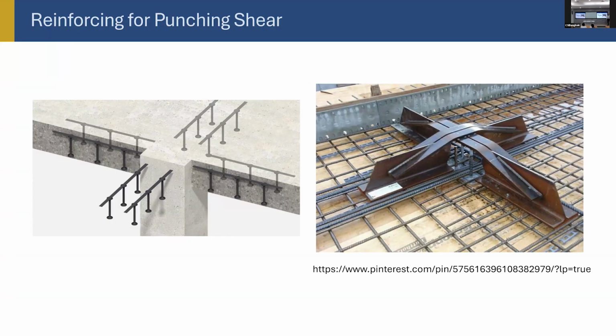So people are really taking a lot of care that the slab should not fail at the top of the column. This shear stud arrangement is now common, people are doing that. And look at those bottom large diameter bars. See this? This is what I'm talking about. These bars are designed to hang the whole slab if it collapses.